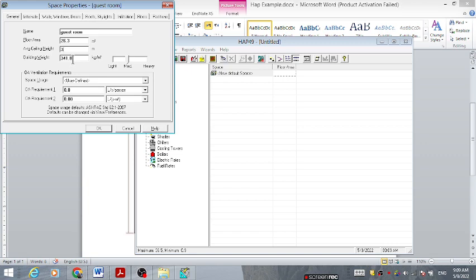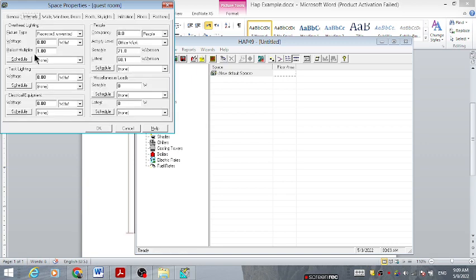Okay, building weight, it's medium. Brick, it's medium, acceptable. Now the other window is about internals. What are your internals? First one, lights. As we know, electric lights are very economic and they do not generate a lot of heat. So let's say it's 10 watt per square meter. Fair enough.